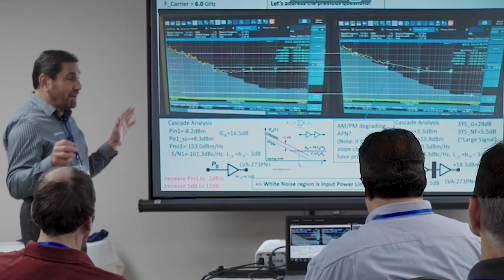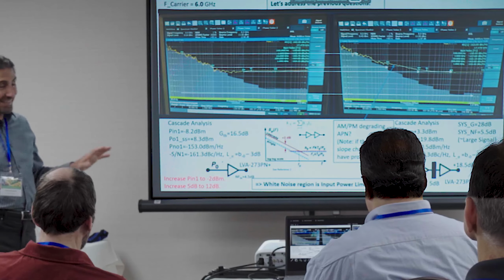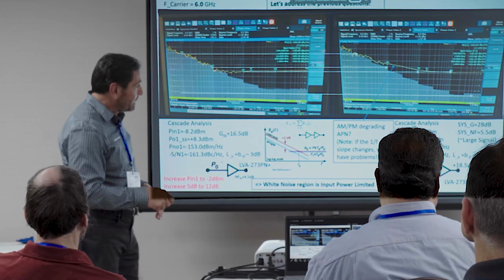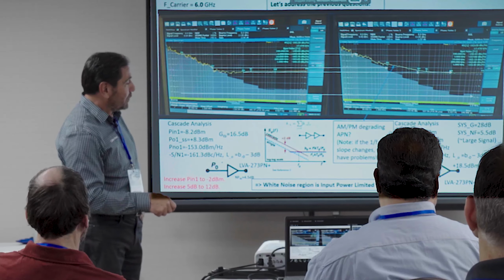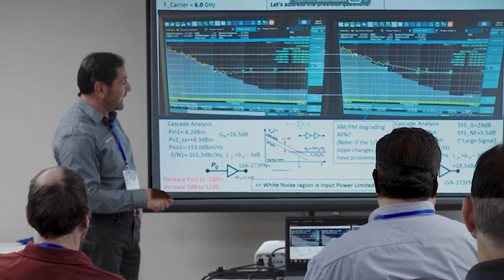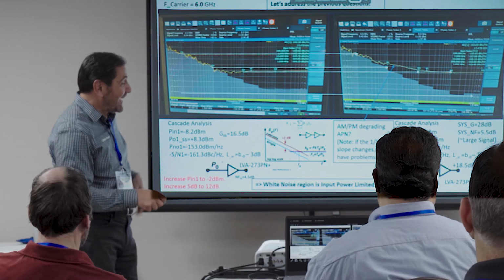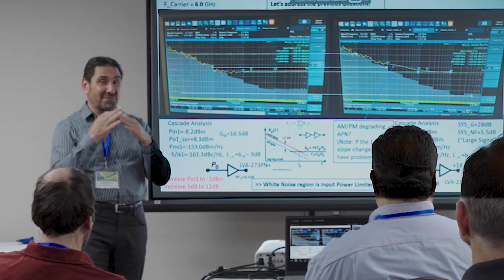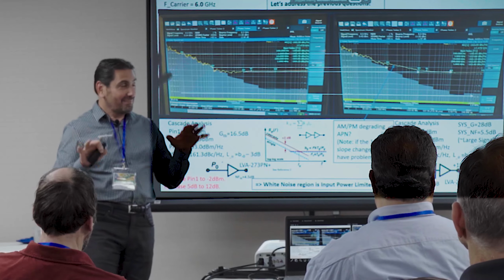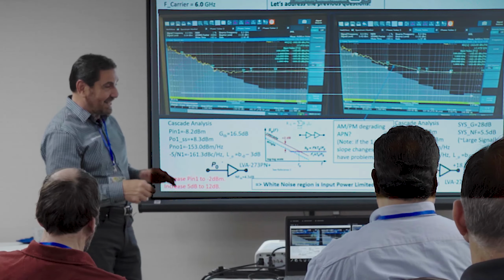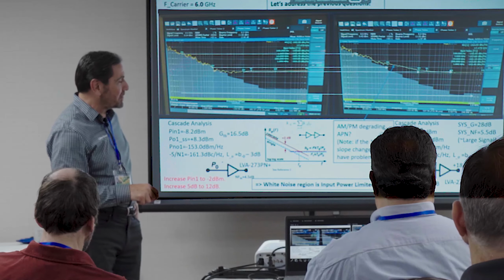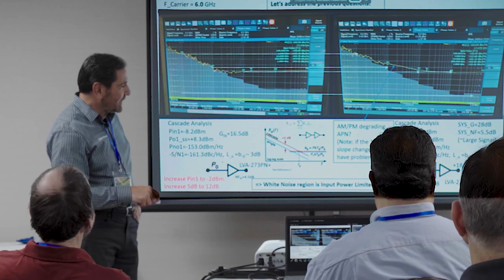And again, I don't know anything about phase noise. I go through my standard cascade analysis formula, and what do I get? I get minus 160.3. I have plus 3.3. I get 19.8. I'm a little compressed here. So here we have to understand that it's not exact because we are compressed here. But we calculate it nonetheless.